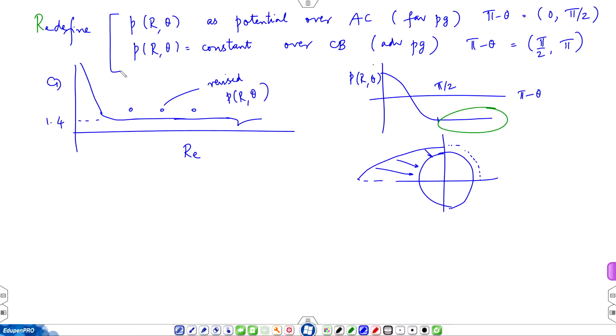This observation, is it universally valid, that in favorable pressure gradient? So, comparison with experiments tells us that when the field has a favorable pressure gradient, potential theory will hold. Can we test it in any other geometry? For a flat plate, pressure gradient is 0. There is no variation in pressure.